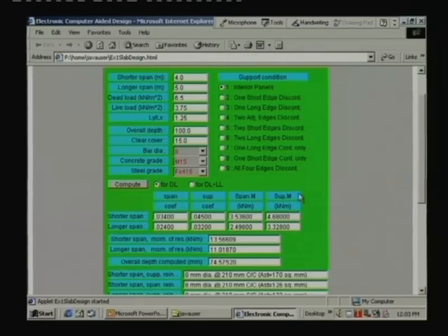So we have 9 different cases as per Table 26 of IS 456:2000. For all the cases, I have made a table internally with all the coefficients alpha x, alpha y for Ly by Lx.